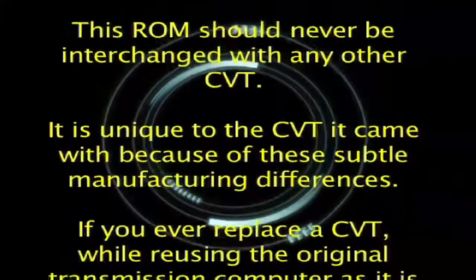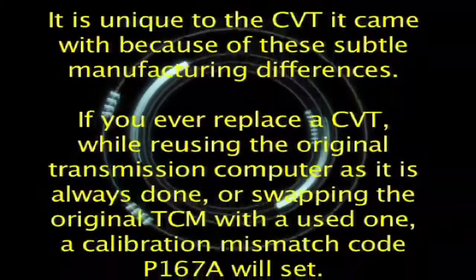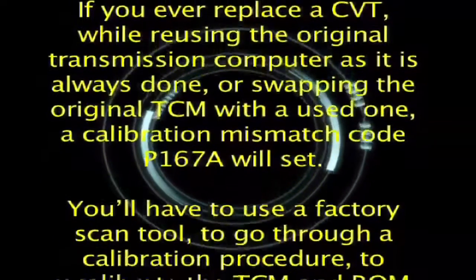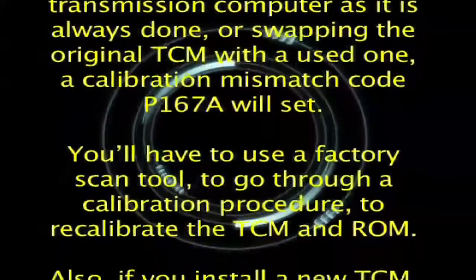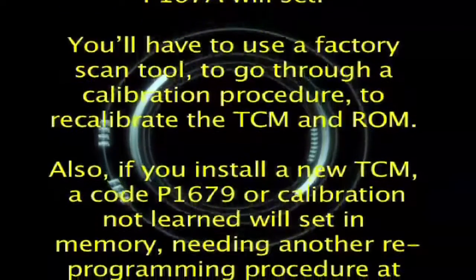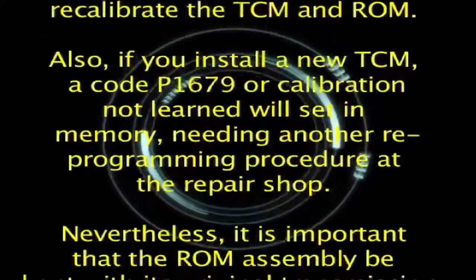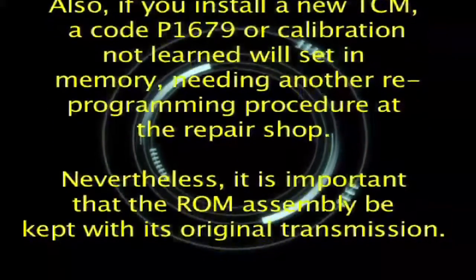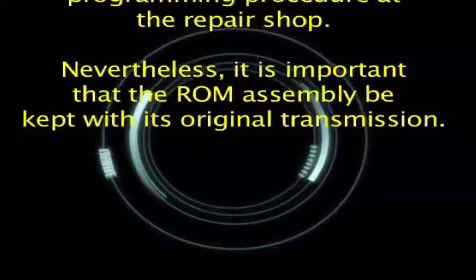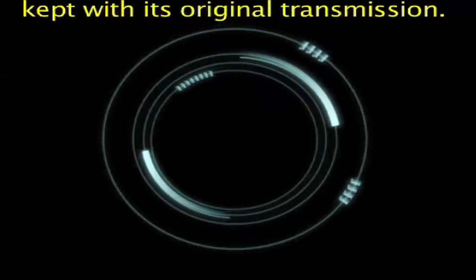If you ever replace a CVT while reusing the original transmission computer, or swap the original TCM with a used one, a calibration mismatch code P167A will set. You'll have to use a factory scan tool to go through a calibration procedure to recalibrate the TCM and ROM. Also, if you install a new TCM, a code P1679, or calibration not learned, will set in memory, needing another reprogramming procedure at the repair shop. Nevertheless, it is important that the ROM assembly be kept with its original transmission.